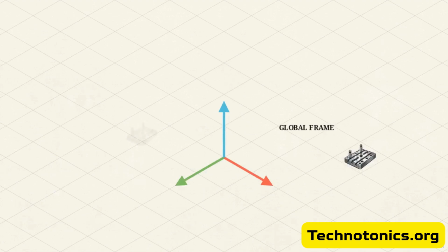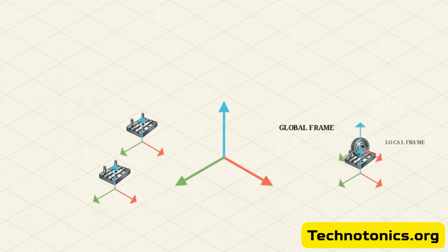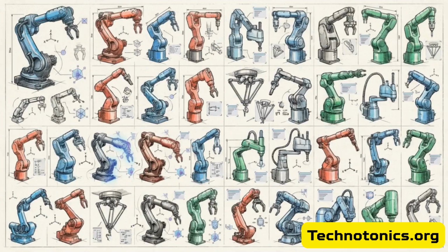The first layer is geometry. We import raw CAD data for fixtures, parts, and tooling, building the virtual work cell to mirror the engineering design. Next, we align coordinate systems and reference frames across the cell, locking in exact spatial relationships. With the environment set, we select the hardware.